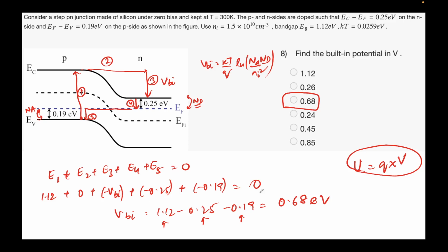Even if you can do that mathematically, but not just that. If you are given a band diagram, you can tell the built-in potential, which to put it very crudely is the amount of bend you see in the band diagram. Remember, this analysis that we did here is true even for non-abrupt junctions, because I'm doing nothing, I'm just traversing, and energy is a more true concept than the mathematics that was involved to arrive at this expression. So just please keep that in mind.